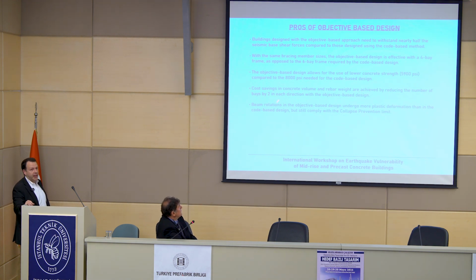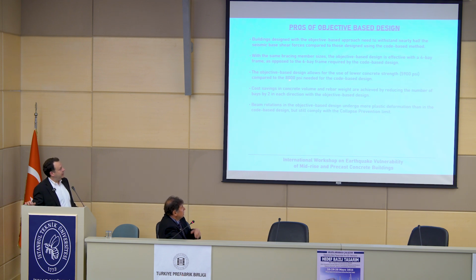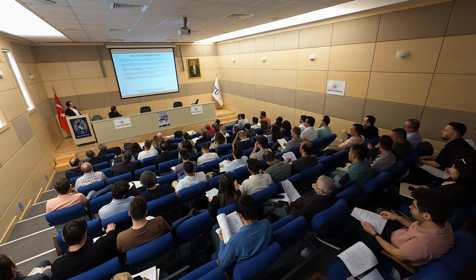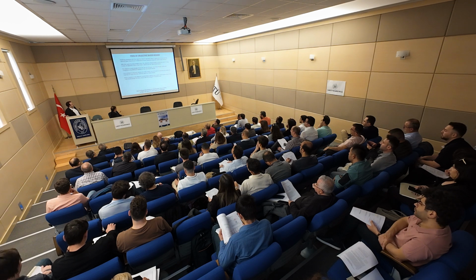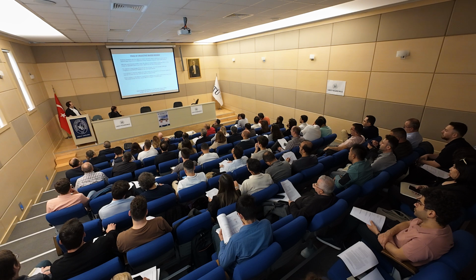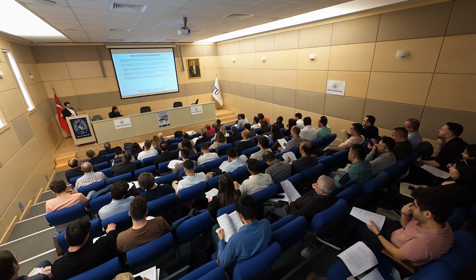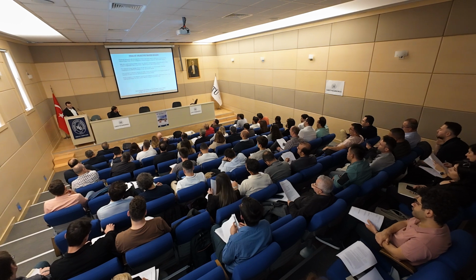In this particular design, for the code-based design to work with these dimensions, we had to take advantage of higher concrete strength. So this is 40 megapascal, this would be 55 megapascal. So with an objective-based design, we can just work with the same concrete strength throughout. So that's another advantage.